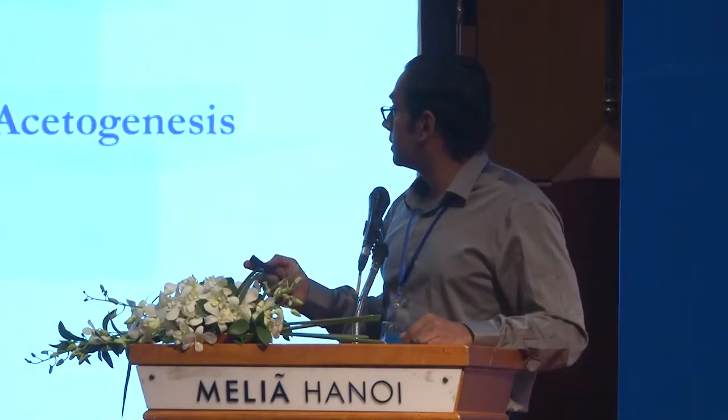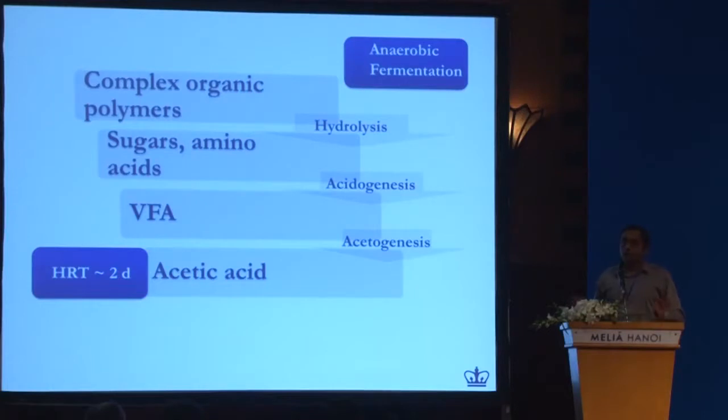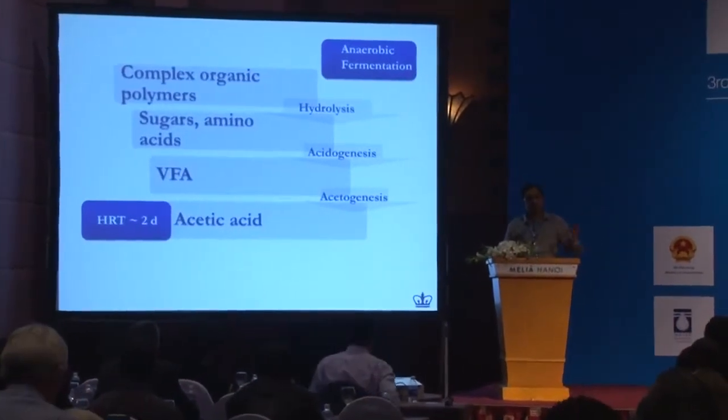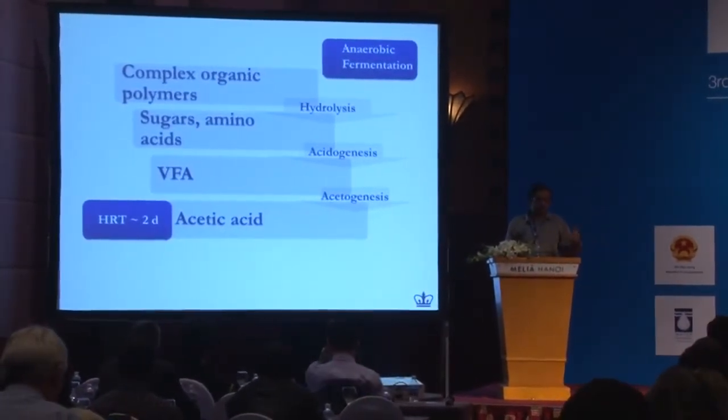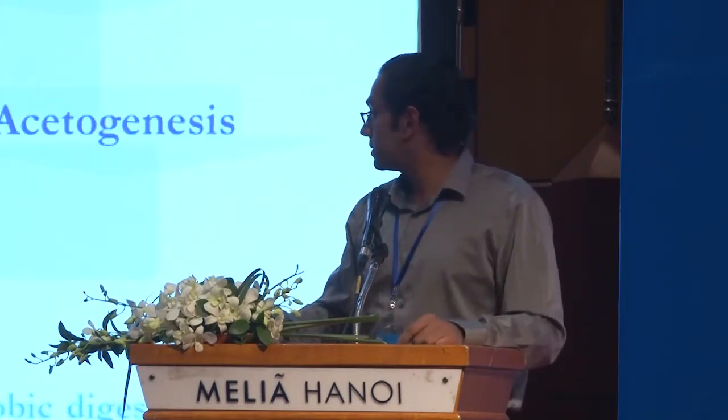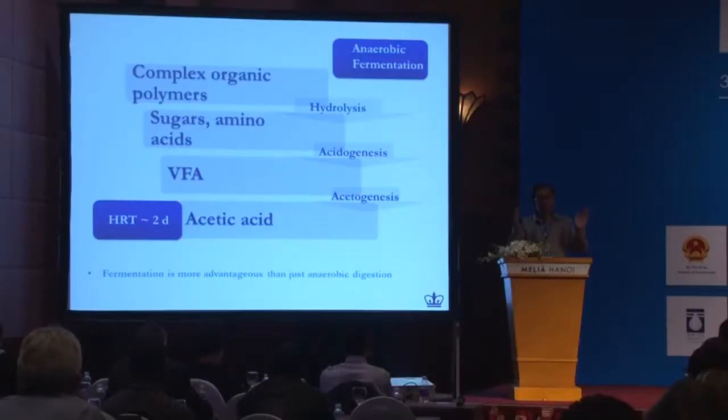This is anaerobic digestion. Now, if you look at anaerobic fermentation, the only thing we are doing is we are taking out that last step of methanogenesis. And because all the other steps are relatively more rapid, we can get fermentation to acetic acid and some other short chain acids. Again, it depends on temperature, but even 1 to 2 days. So one of the advantages is that when we rely on this fermentation-based platform, we are not looking at a retention time of 15 days or 10 days. We are looking at something which is quite short.